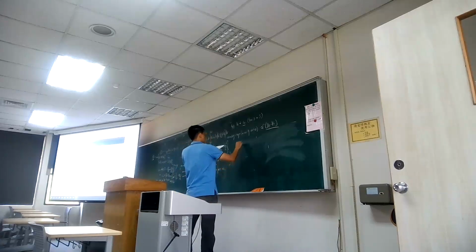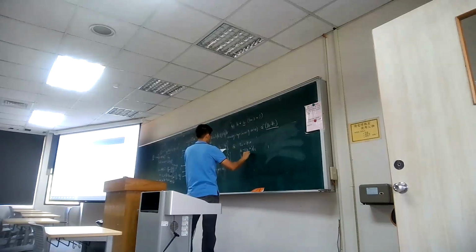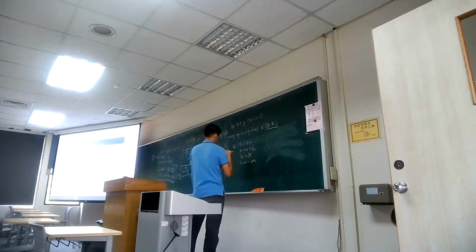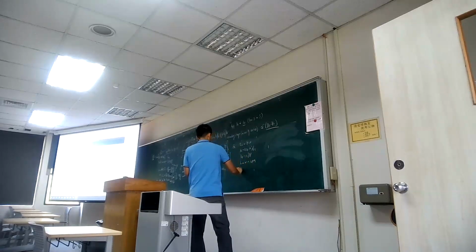I think there will be a quick example, but I think that's boring. So for instance, here's the example. If you think t_ox is 8 nanometer, and your μ_n equals 450 cm²/Vs, your Vt is typically 0.7 volt. L_min, what is the channel length? It's 0.4 micrometer. Find the C_ox and the